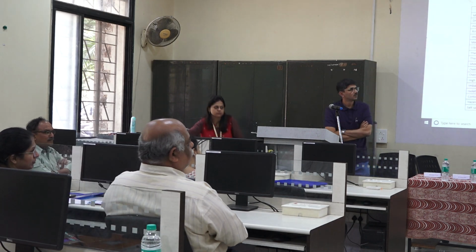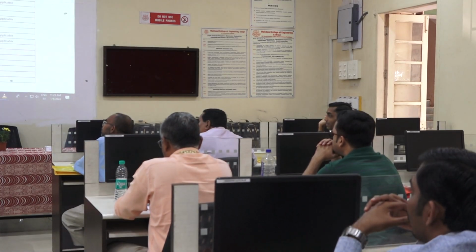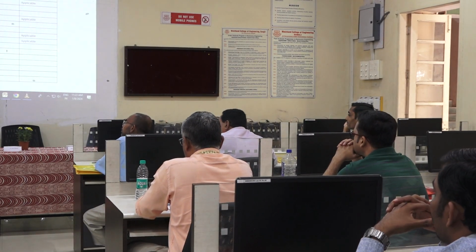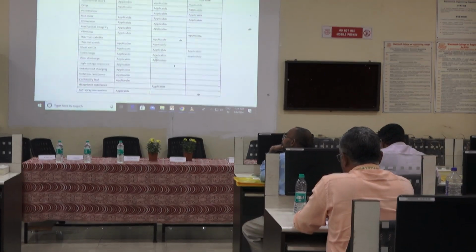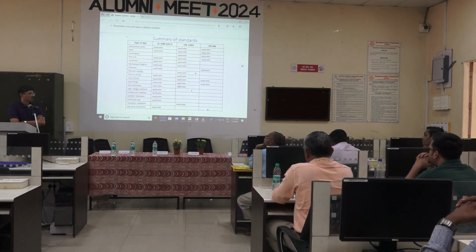So is braking still mechanical? Braking is category B, mechanical plus electrical. But yes, mechanical is always the preferred option because it is a fail-safe brake. If you go to locomotive brakes, if your air system is not charged, the locomotive doesn't move by any means. It is locked.